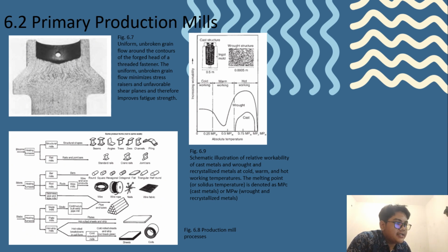And ingot breakdown. Many ingots continue to be statically cast because not all ferrous and non-ferrous metals are capable of being continuously cast. Due to their relatively coarse and inherently weak microstructure, the temperature range over which ingot structure can be forged is very limited. Typically, ingots must be hot worked to refine the grain structure in order to allow recrystallization to occur.